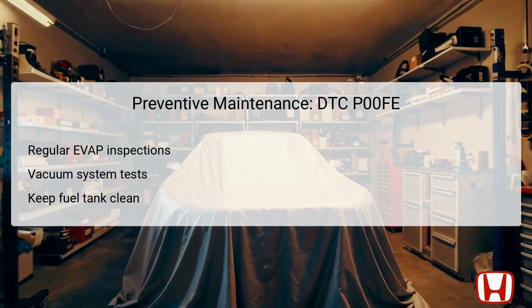To mitigate the risk of encountering DTC P00FE in the future, implementing regular preventive maintenance is advisable. Schedule routine inspections of the EVAP system to detect any emerging issues before they escalate. This includes conducting vacuum system tests to ensure proper integrity, as well as monitoring for any signs of leaks or